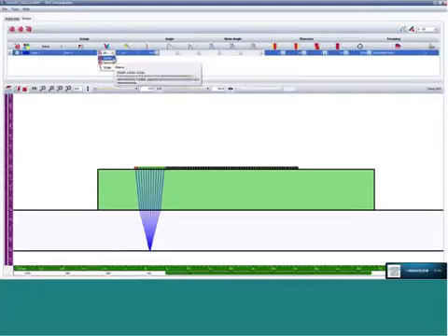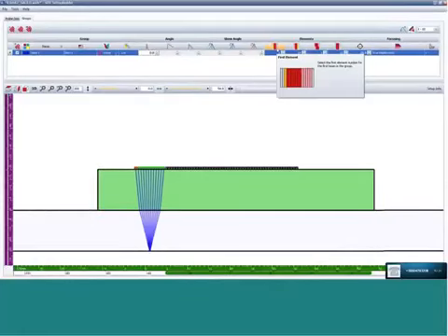We're going to select a linear scan, which is defined by the same focal law multiplexed across the entire probe, whereas a sector scan would be a series of different focal laws from the same elements within a probe. We select the longitudinal wave velocity, the angle of 0 degrees, the start position of the first element.